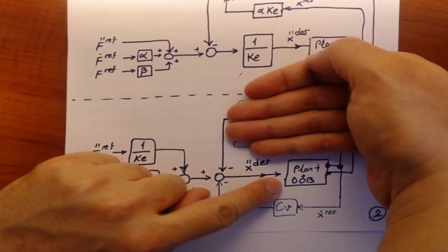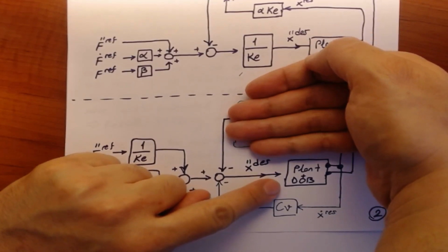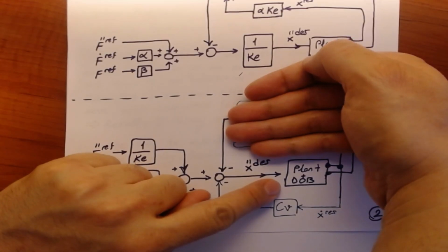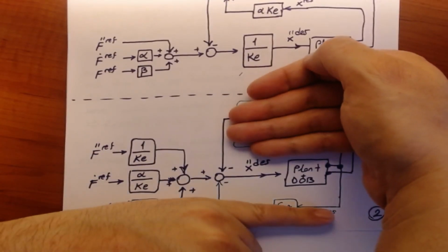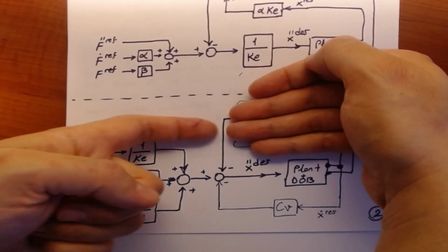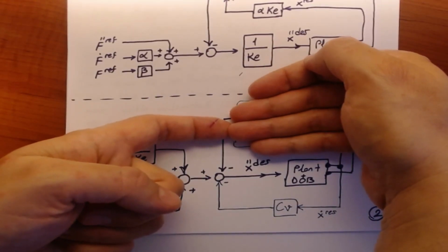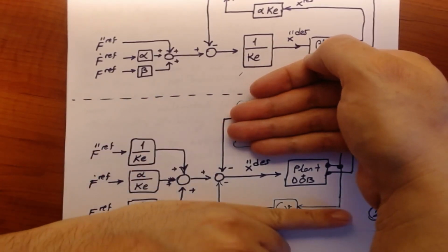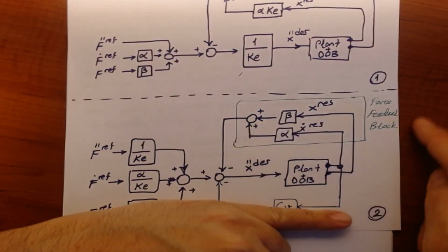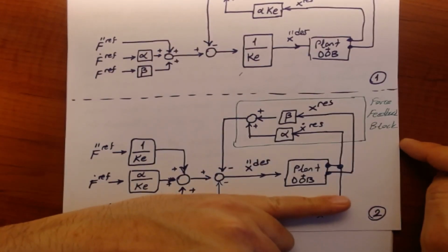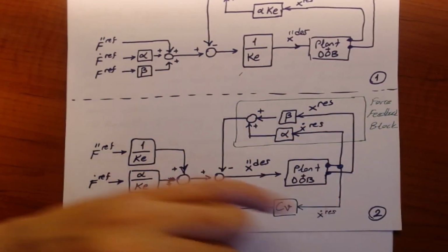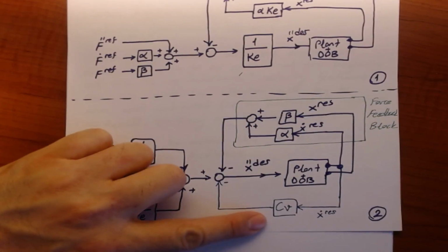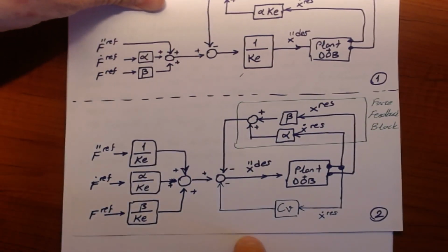So this means that your system is bounded, and it goes with certain velocity until it reaches the contact point with the environment, and after the contact point the response velocity reduces dramatically, because as you approach the environment and as you contact, your velocity reduces dramatically. So this channel will be then passive, and then this channel will be active. Your force feedback will be in action, and you will try to start carrying out the force control. So adding the velocity feedback has this advantage I've been showing here.